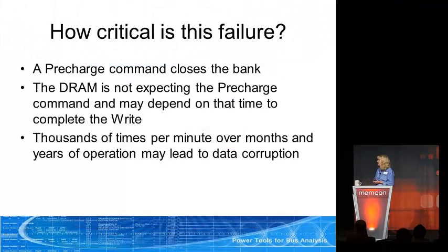So how critical is this? Well, a precharge closes the bank. So the DRAM is not expecting that precharge command and may depend on that time to complete the write. Thousands of times per minute over months and years of operation could lead to data corruption.